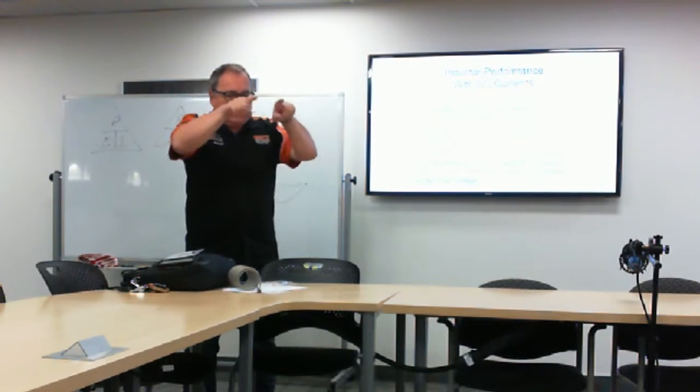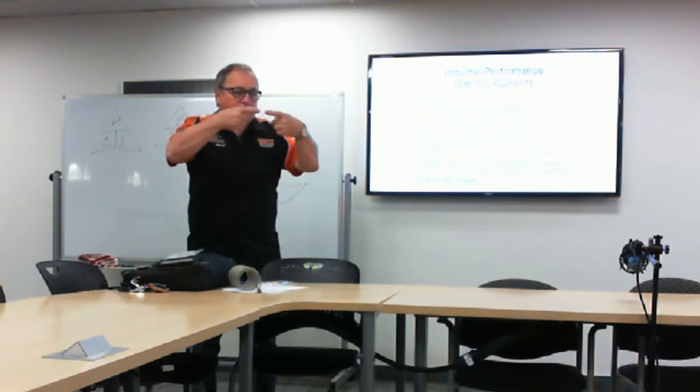The magnetic field begins to collapse and there's a rush of current in the other direction. So when you have a coil and you energize it with DC and you remove the DC, if you connect both wires together, an enormous amount of current goes through there because that field is collapsing, and it's a magnet cutting a conductor.